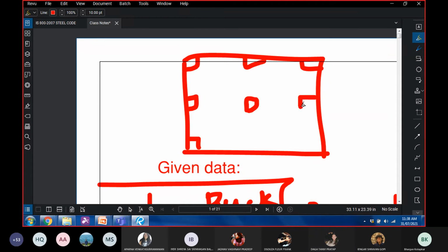No. Okay. So just imagine that these are your columns. So this is your central column. Your span in all the directions is the same, and therefore you will expect this column to be predominantly subjected to axial force only. Because there is no unbalanced span, there is no different span, there is no unbalanced moment. And therefore, you can expect this to be a compression member.